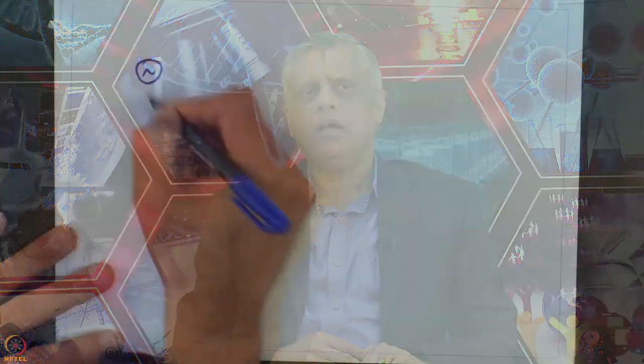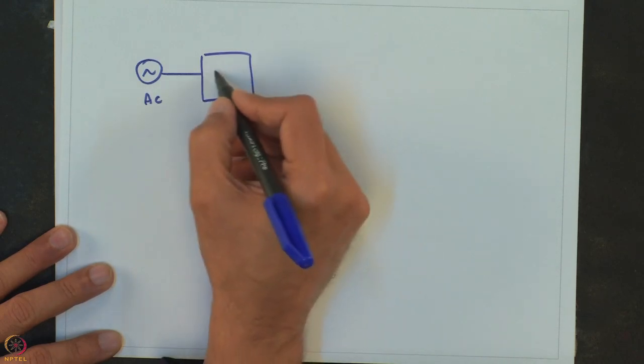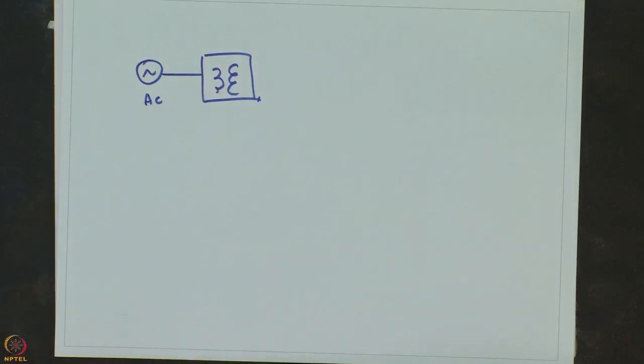Okay, now let us just take the examples of linear regulators and the switched mode power supply, which exhibit a stark difference between the losses incurred by them, a fact which has revolutionized the field of power electronics. These supplies are fed by an AC source, okay, usually, and you have this transformer, because the voltage that is actually coming from the AC line, it may be very different from what exactly you want at the output.